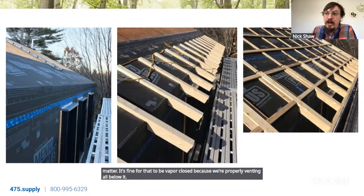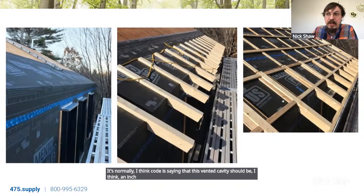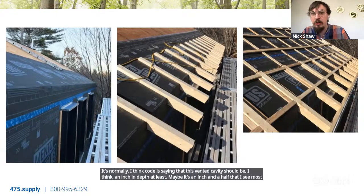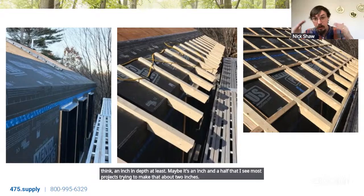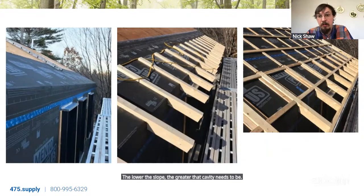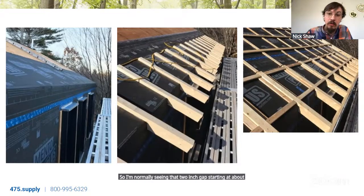It's normally, I think code is saying that this vented cavity should be, I think, an inch in depth at least. Maybe it's 1.5 inches. But I see most projects trying to make that about 2 inches. The lower the slope, the greater that cavity needs to be. So I'm normally seeing that 2-inch gap starting at about 3/12 pitch or greater.